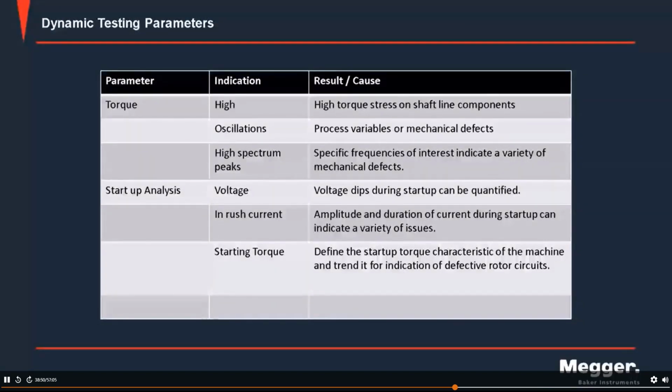Startup analysis, looking at a motor during that starting cycle, right? We talked about how aggressive that is on the motor insulation system. The high inrush current, the high I squared R loss from that 10 times current flow, that up to 300% torque, causing the windings to wiggle around and abrade away. And of course, voltage during a startup dips, and that voltage dipping can lead to longer startup times, basically is what we're worried about there. Longer startup times mean a longer period where we're sustaining that high inrush current, which is definitely not the best idea. That high inrush current is producing all that heat.